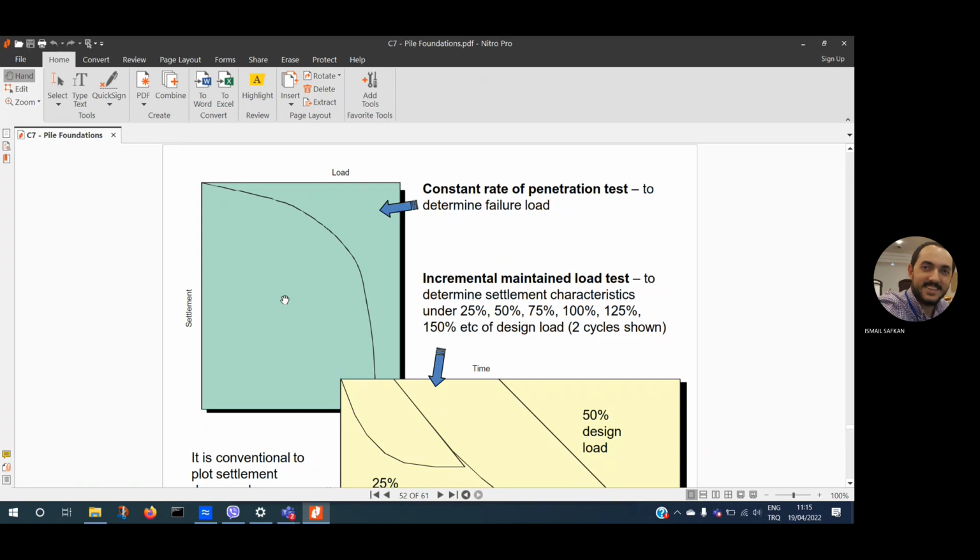You might have huge stress capacity even after it yields or shears, but if you don't satisfy the settlement condition, imagine that you reach this level of strength after your pile has penetrated into the soil, and now there is this huge settlement. Not realistic. For your building, having this much settlement of your piles after you reach this level of strength is useless.